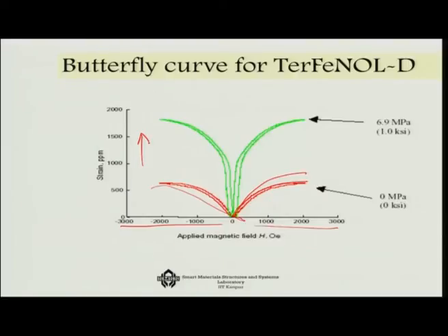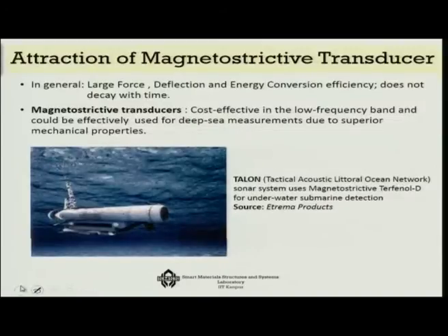To do that, what we use is a bias current, and we operate across that bias current. Suppose somewhere this is my bias magnetization, and we keep that fixed, and then we take a bandwidth on which, as we change this bias, it is going to show relatively either less strain or more strain. Thus you can generate your own magnetostrictive transducer. So that's the advantage of this system.